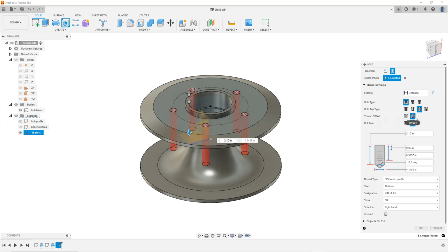And that's going to prevent us from putting a tap into the bottom of the hole and breaking it off. Okay, so anyway, this is going to give us our hole depth right here. Okay, and these are going to give us our thread parameters.